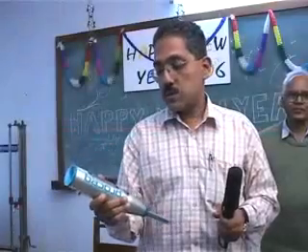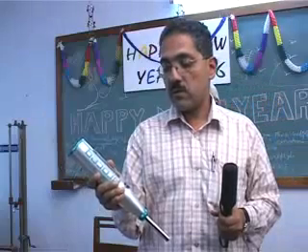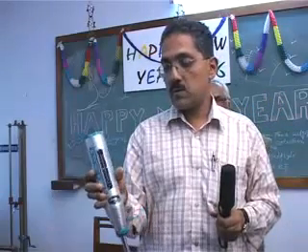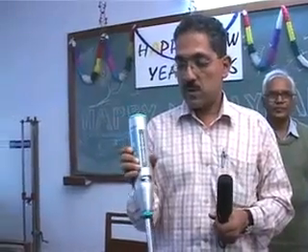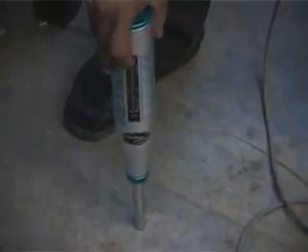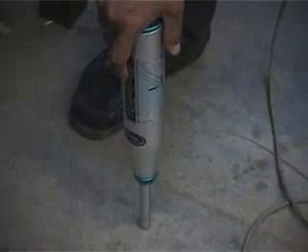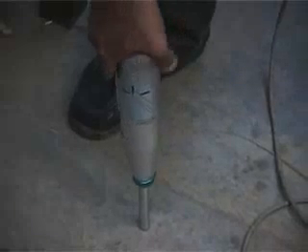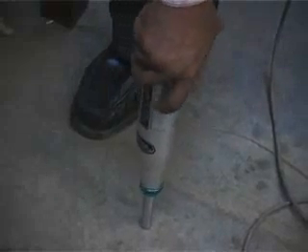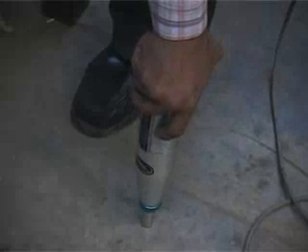This is the instrument that we are going to use for non-destructive testing of a rock mass. It's a very simple index really. We are going to push the instrument in, and we have to make sure that this particular knob is pressed when the rebound occurs, in order to measure the rebound value, and the reading is going to appear on this